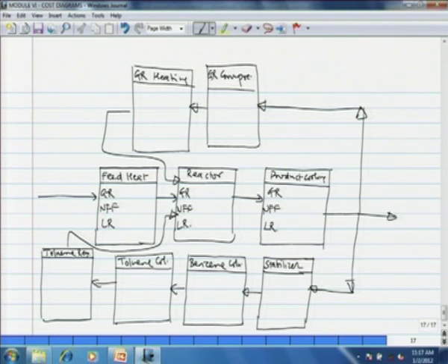The total toluene loss is 13 moles per hour, 8 moles in the form of diphenyl and 5 moles in the vapor. So, the total loss of toluene is $1,691,000. Total loss of hydrogen is $2,160,000, out of which